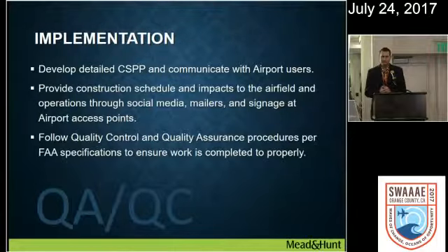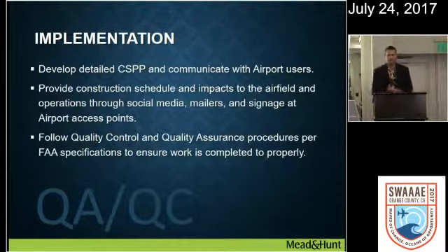So one other element that a lot of these changes has caused, or not caused, but the removal of pavement markings. On an airfield, the pavement marking requirements change, or your airport design group changes requiring the markings. It has been a challenge. With the new advisory circular, you have to remove the markings in a box type fashion. And so I just wanted to share a few lessons learned on that when you're trying to implement these new projects,